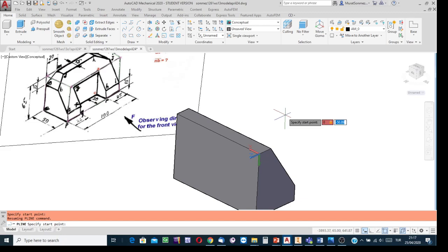Ordinate: since the y-axis is in the down direction and the point relative to the topmost level is at a lower position, 15 is positive. Delta y is 15. Write 15, press enter. Yes, that is the starting point.